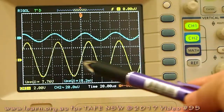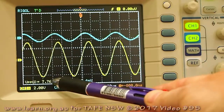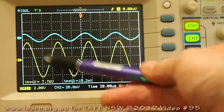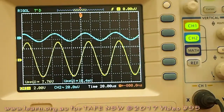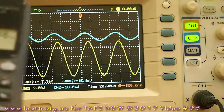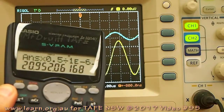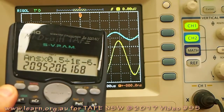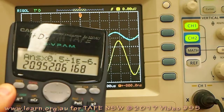So where I had 12 volts peak in my equation before, I'd have to take half of 7.7. So let's call it a shade under 4, 3.8 volts or something like that. I'd have to put that into the equation, and we'll find that the frequency of operation will indeed be much higher. Okay, I've just done the new mathematics on that. I've put in 3.8 volts peak instead of 12 volts peak into my equation, and now it's telling me I should be able to go to 21 kilohertz safely before I start to get slew rate distortion.